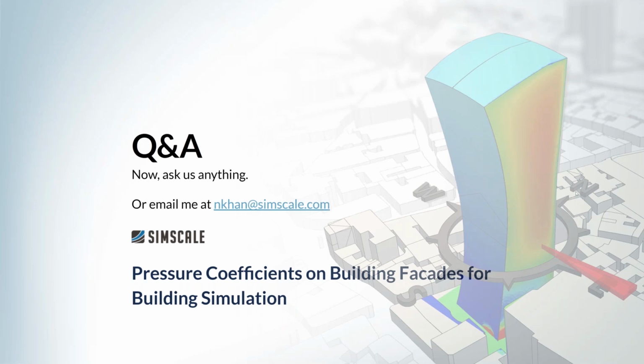The next one was, what about the mesh independence of this model? So of course we've done the validation, and we know approximately at these city scales where the mesh refinements should be and what they should be, and we based the model upon those. Of course, if you're going to do your own project, then you need to do your own mesh independence study, because it will always be different from case to case. And we do show a mesh independence in the validation case as well.